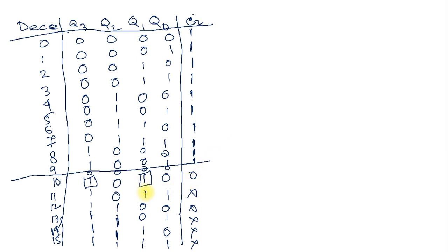So if we check once that Q3 and Q1 simultaneously, when both are 1, then at that condition Q0 and Q2 may be 1, it may be anything. But simultaneously, if we track this one, at the stage when we receive the sequence Q3 and Q1 simultaneously 1, that time we can change the clear from 1 to 0. This is one method.